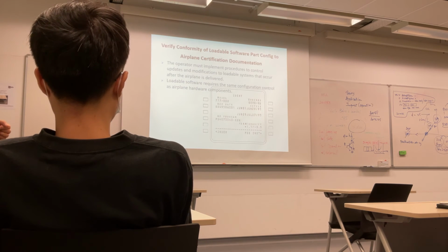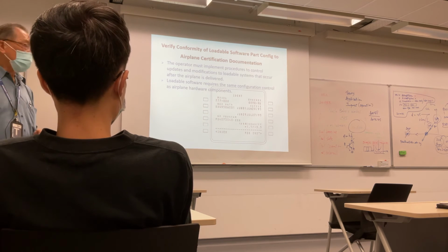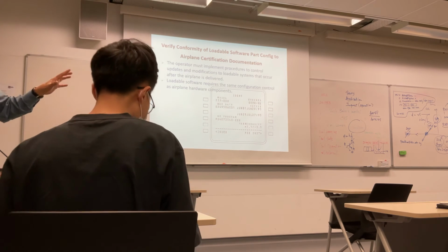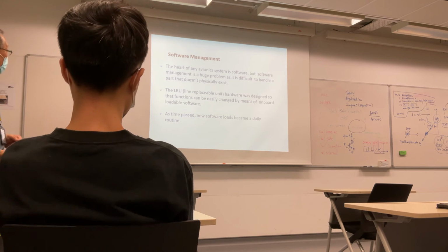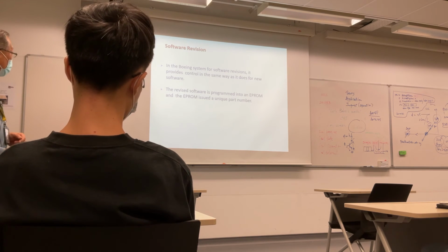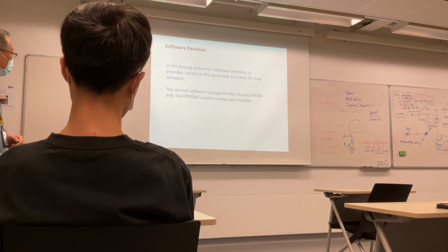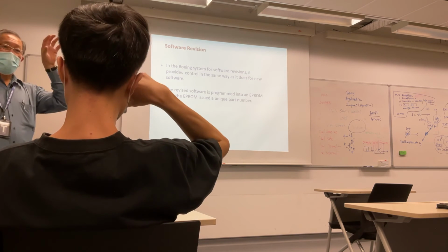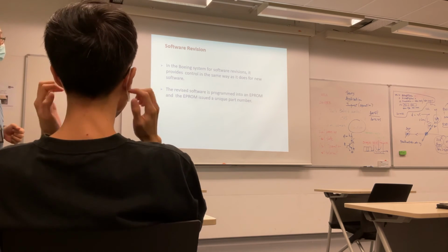I mentioned this one is a repeat. But the good thing is that when you load a software, the LRU will tell you the software status. This is the display; you can actually read the software status. The aircraft has this system to do that. These are all the processors. So today, revised software is programmed into EEPROM, of course, we use EEPROM nowadays, and it's issued as a unique part number. That means if a program can be updated when the aircraft is online, you need to have a separate number.